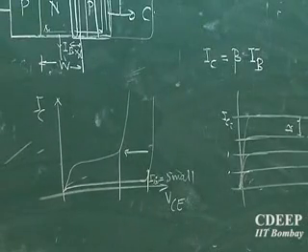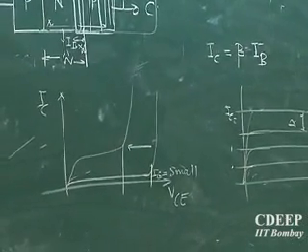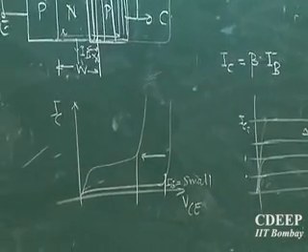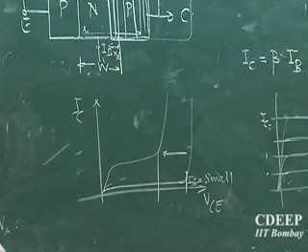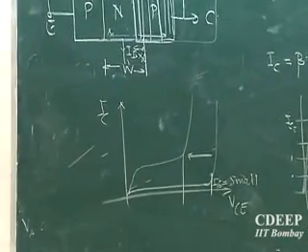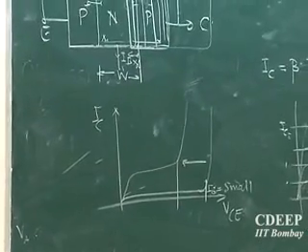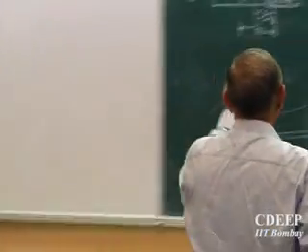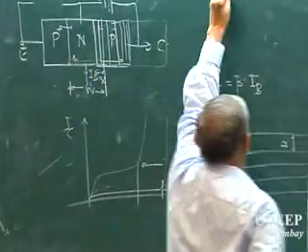If I now have base current flowing, that is, the base emitter junction is forward biased and some current is flowing in the base, why do you expect it to have an earlier breakdown? If you have larger base currents, that means the charges in the base were higher. Those transiting the base collector junction depletion layer are also large in number. Is that point clear? I repeat. This is my depletion.